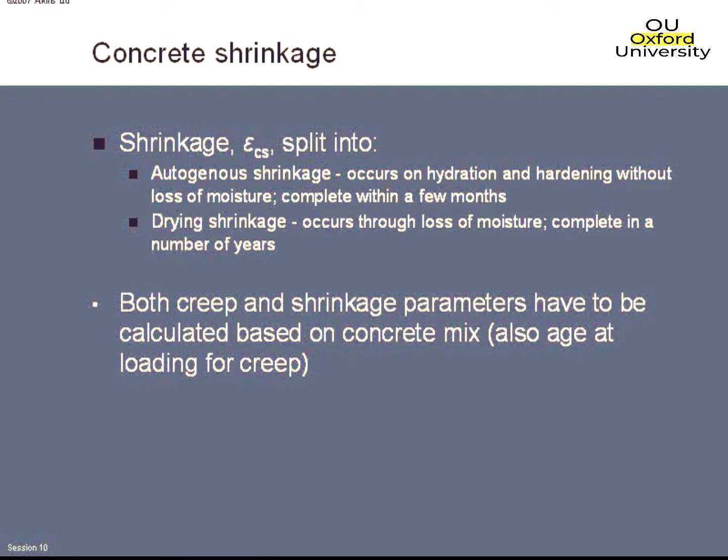So whilst in theory you add the two components together, you do need to take account of the times that you're actually considering. If you've got something just sitting around doing nothing before you've pre-stressed it, you may find that a lot of the autogenous shrinkage has disappeared and it's not actually affecting anything.